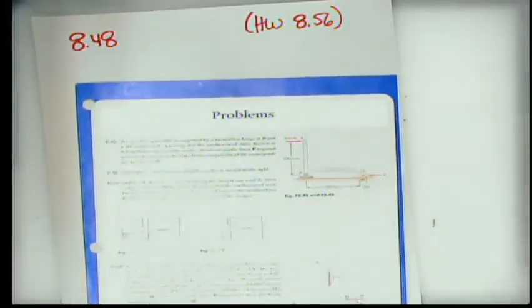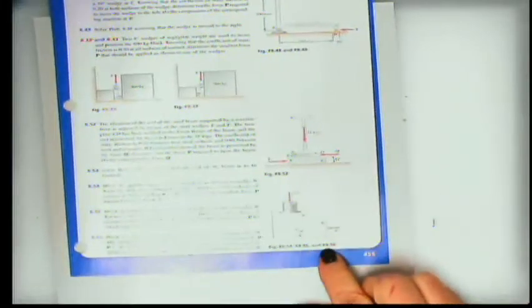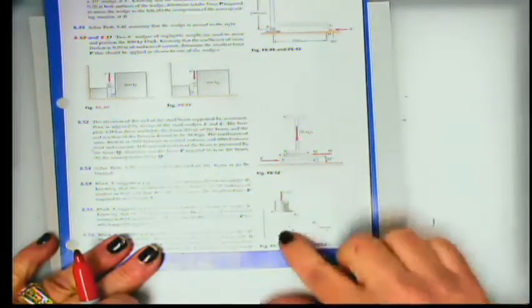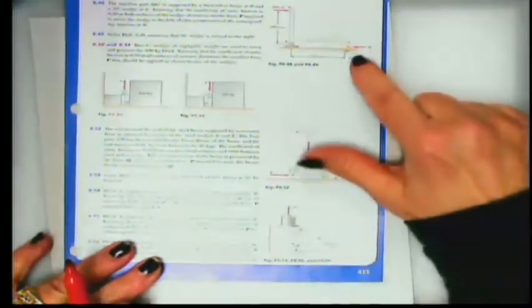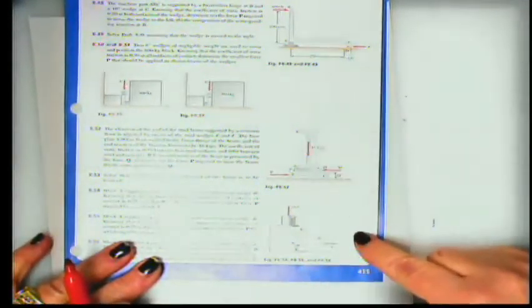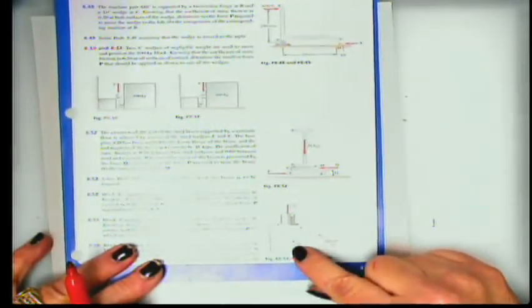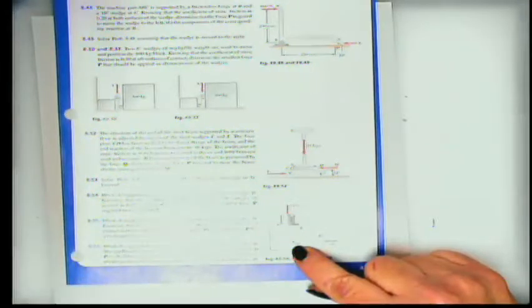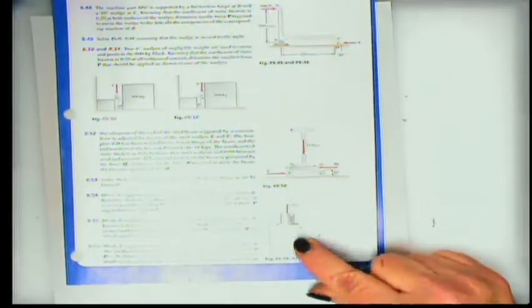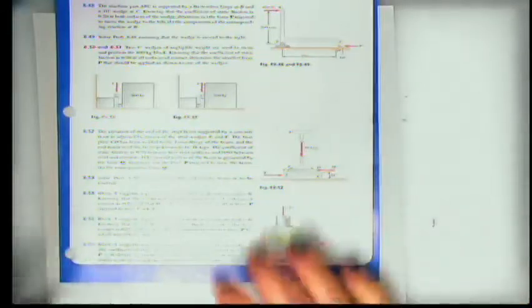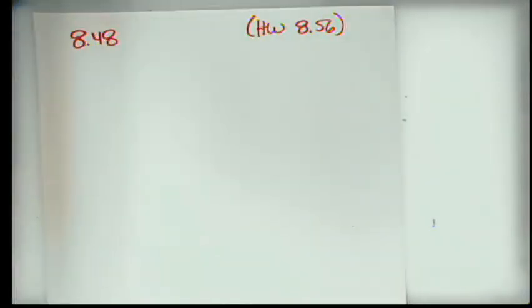All right, and similarly, when you work problem 8.56, you'll see that there is an angular relationship here between the contact of the blocks. The thing to remember in each of these is that the friction at that contact surface is equal to a coefficient of, if it's moving, dynamic friction, or up to the coefficient of static friction times the normal force, and that the normal force is always directed normally or perpendicularly to that surface of contact. So those are the factors that you need to bring into your analysis.